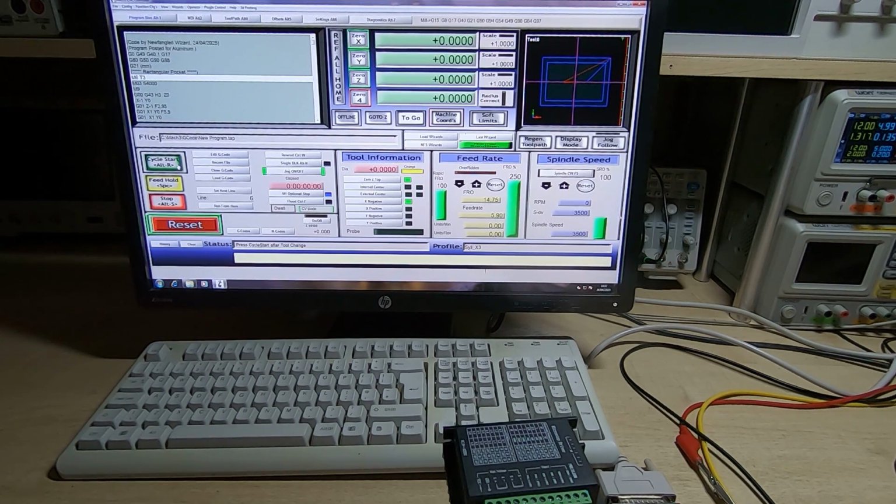When you click on the cycle start button, MACH3 will then run the M6 end macro. But it doesn't do that until you click on the cycle start button to restart the process, which might sound a bit odd because you'd expect it to go straight back into the G-code, but it doesn't. It will run the M6 end macro first.